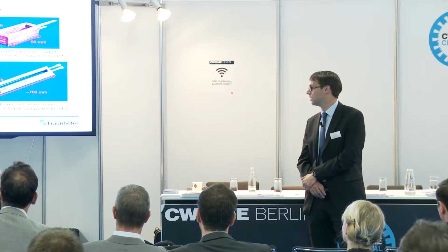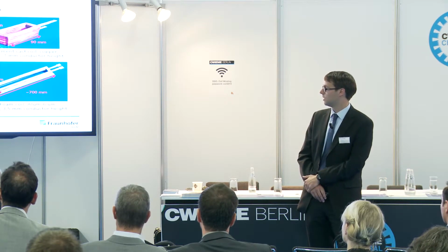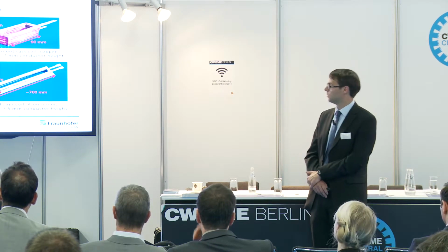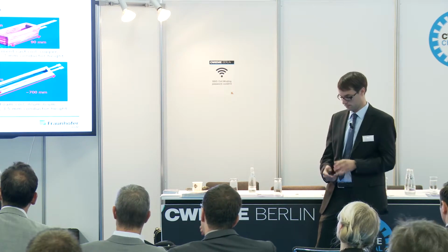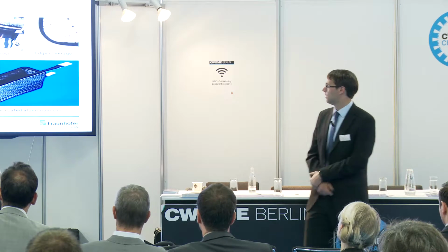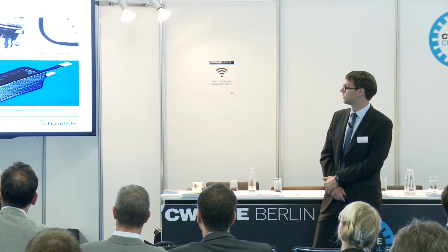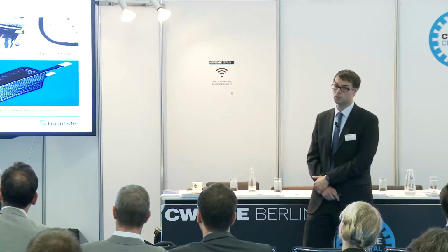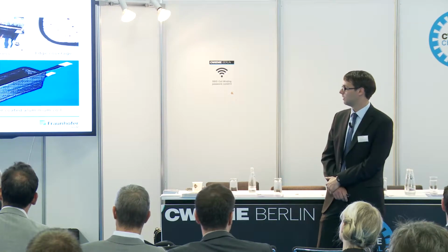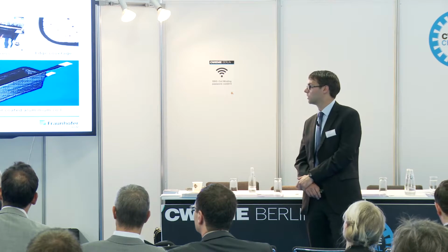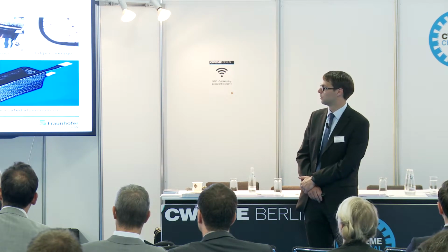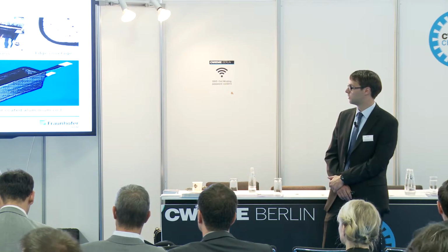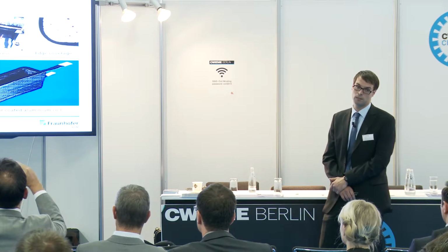We are able to realize coils in different materials. In copper, we realize conductivities of 46 to 47 megasiemens per meter, and in aluminum, we realize from 34 to 36. The insulation of the coils is afterwards done by different processes. We can use EPD processes or powder coating processes, depending on the wanted layer thickness. With powder coating, about 40 micrometer, with EPD processes from 20 to 30 micrometer. And we can realize insulation strength of about 2 kilovolts with 180 degrees temperature stability.